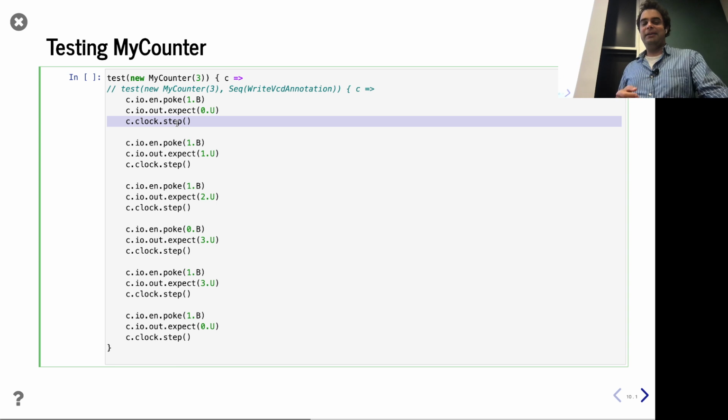And so for today, you definitely have to use step because we're doing sequential circuits where registers change every cycle. But even if you weren't doing registers, sometimes you still use step inside your test benches to make time advance, so it makes things more clear for the output and for parsing it. Right now, we're just running a test case, and we're going to say, hey, look, it passes. At the end of today's lecture, we'll cover both waveforms and printf to get more information out of this.